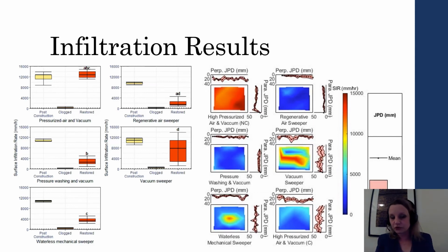So this shows us that if we want to make sure that we achieve uniform restoration, we may want to, especially with street sweepers, where you have rectangular vacuum heads or suction heads, go at least twice and do a hatch pattern. So go one way on the first pass and then perpendicular, or 90 degrees, to that, so that you're going over both joints regardless of their orientation. And this should improve the restoration that you achieve during the maintenance.